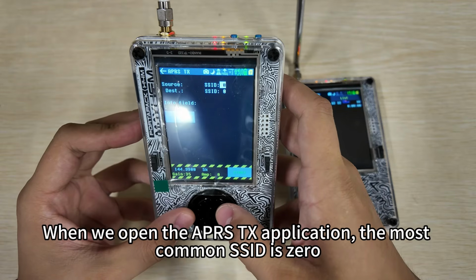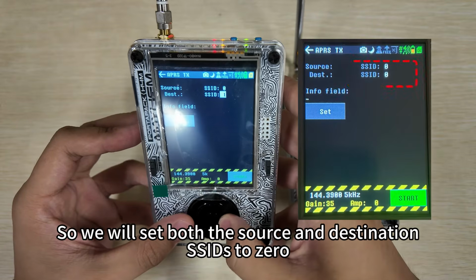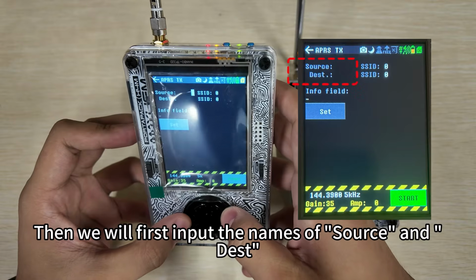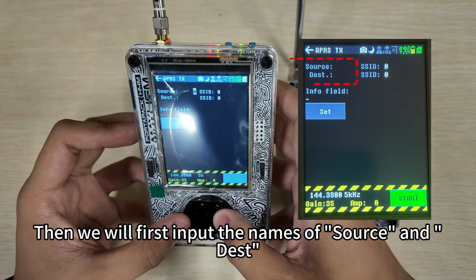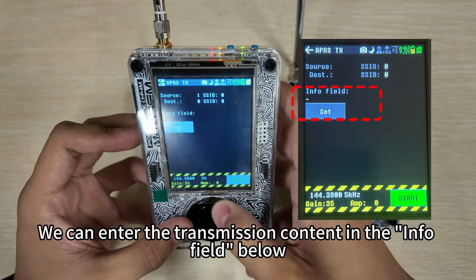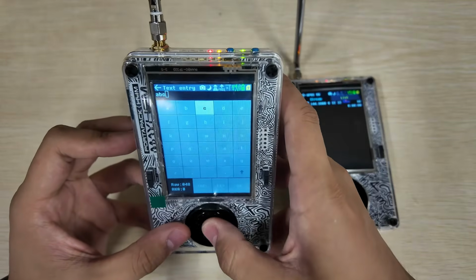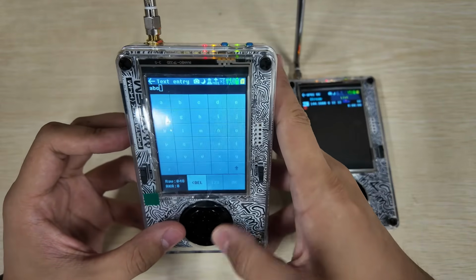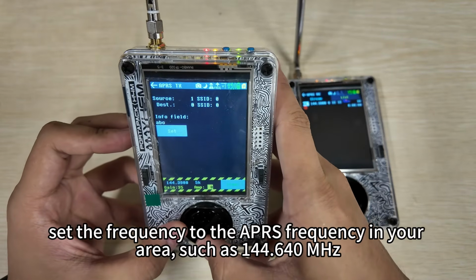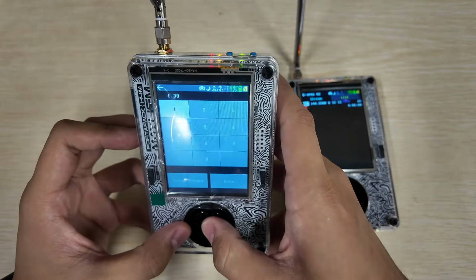When we open the APRS TX application, the most common SSID is 0, so we will set both the source and destination SSIDs to 0. Then we will first input the names of source and dest. We can enter the transmission content in the info field below. Set the frequency to the APRS frequency in your area, such as 144.640 MHz.